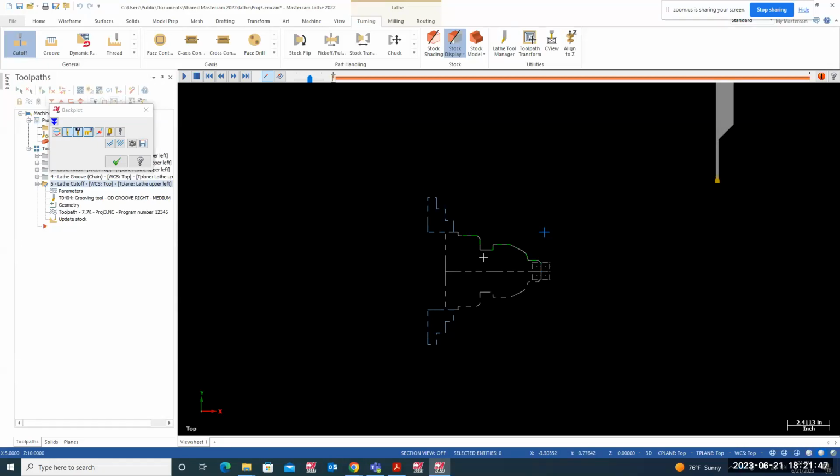No. Because when we're going to set up our machine, we're going to pick up the tool. That's the first thing you're going to measure, guys, manually: my diameter is 4 inches, which is going to be minimum 2 inches radius. So this has to be more than 2 inches. This is something you check physically before you do the setup. But here, everything looks good.